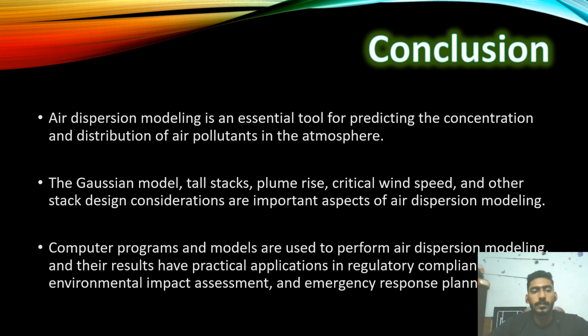For conclusion, air dispersion modeling is an essential tool for predicting the concentration and distribution of air pollutants in the atmosphere. The Gaussian model, tall stacks, plume rise, critical wind speed, and other stack design considerations are important aspects of air dispersion modeling. Computer programs and models are used to perform air dispersion modeling, and their results have practical application in regulatory compliance, environmental impact assessment, and emergency response planning.